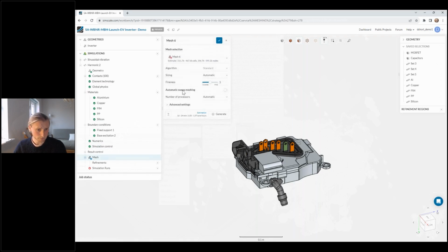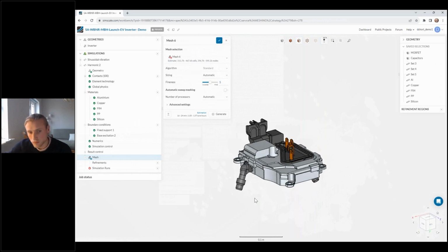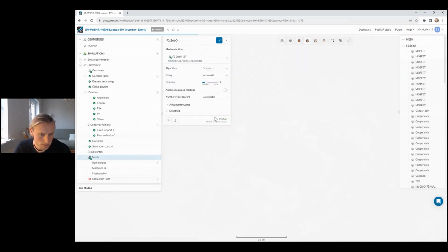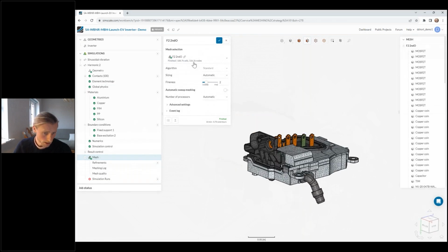Now, in terms of meshing, we can use fully automatic meshing with tetrahedral elements. We also have manual refinement options for creating prismatic or hexahedral elements, for doing surface-based refinement and so on. But for early stage design here, we're just going to go with second order tetrahedral elements for capturing the geometry fairly coarsely to begin with, and then you can work progressively from there. So I've already got a mesh here. That took 10 minutes to create.